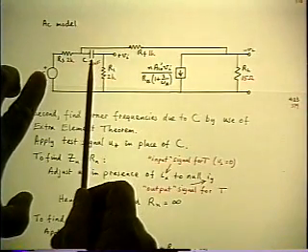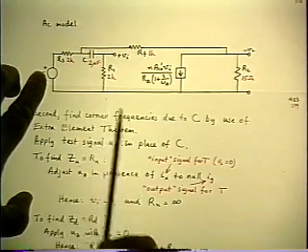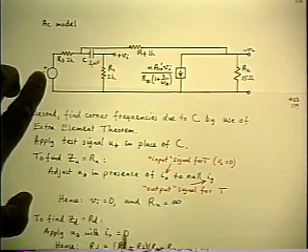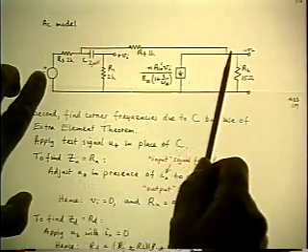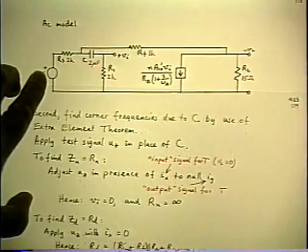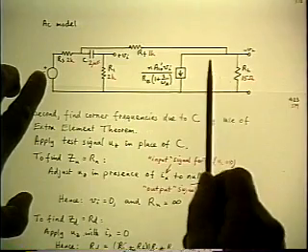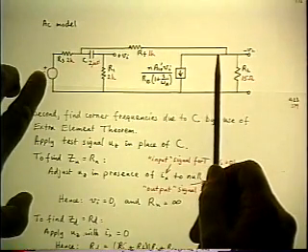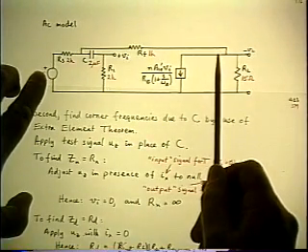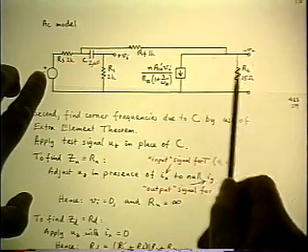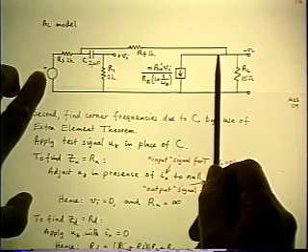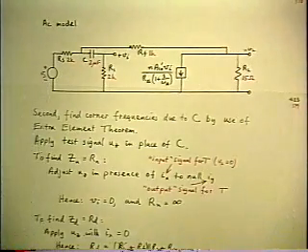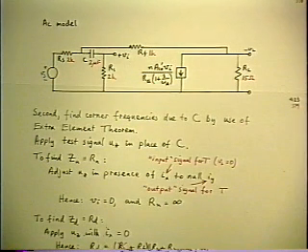If you look in place of the capacitor, you're going to see R1 to the right, plus to the left Rs, parallel Rf, plus RL. And there's no ambiguity at this point because Ix is 0, and Ix is the current in this path. So RL and RF are simply in parallel when Ix is 0. So that's the value of Rd. So that's going to determine the pole.